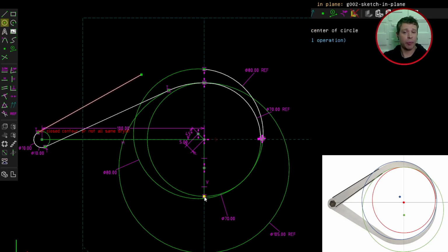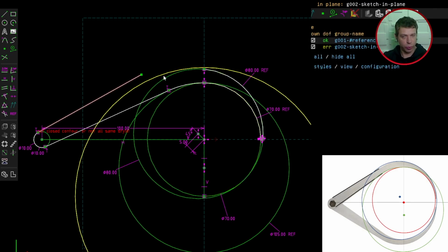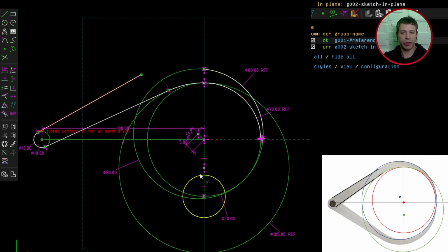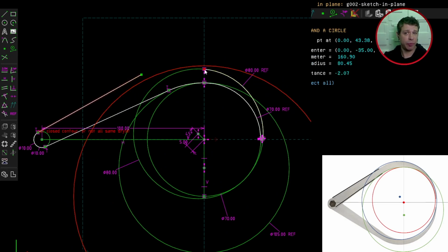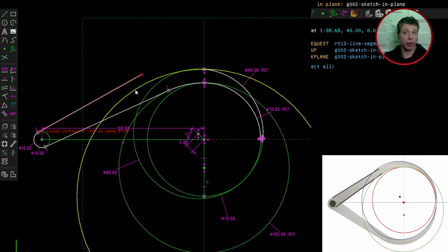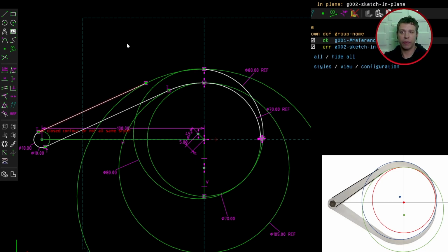So let's see what happens if I select this point and click outwards. It looks like that could work. So I'm going to select the circle, convert it into a guide. The position is currently constrained to this point here, but I need the diameter to be constrained such that this point will be overlaid on top of it. So I'll select the point and the circle and click constrain point on curve. This point will be constrained onto that circle in the same way, clicking constrain point on curve.